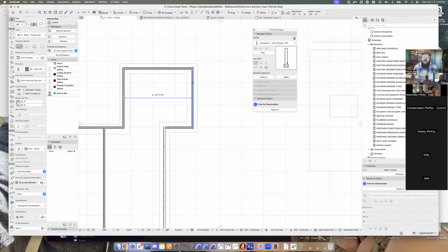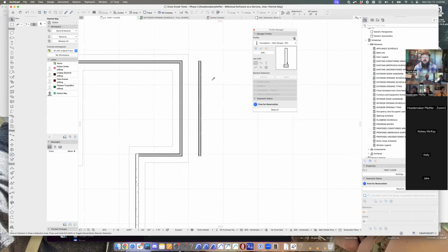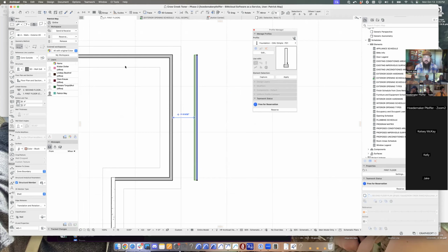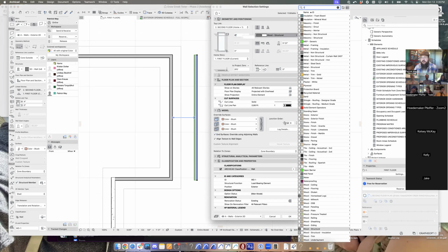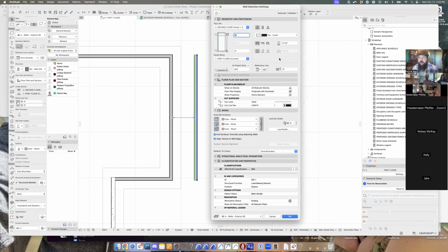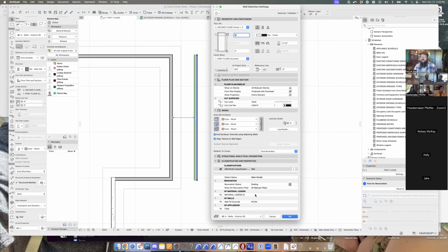So if this is my main wall and this is my finish wall, and I'm just going to put them side by side here, right? If I said that this is my finish wall, and that finish wall doesn't have to be a composite, it can be anything, right? So I could say that this is tile finish. If I had a property in here that said that this is for finish only, then I could say schedule things that are called out as finish only. And then I could schedule out their color, their name, their area, the room that they're in. That becomes a lot more simple.